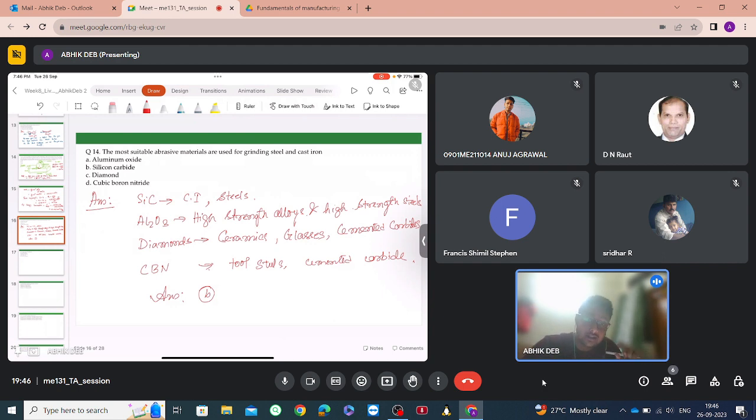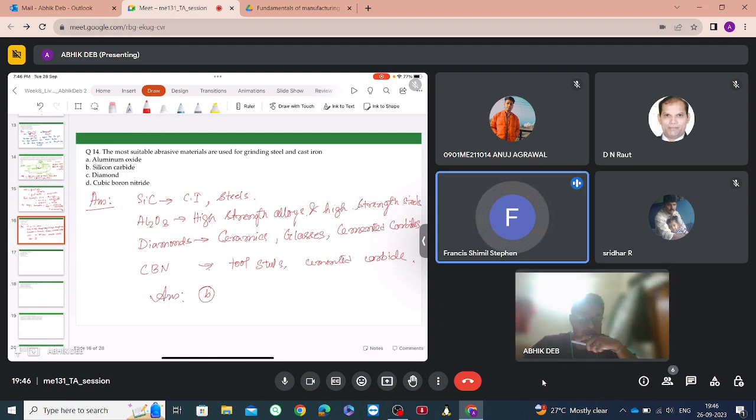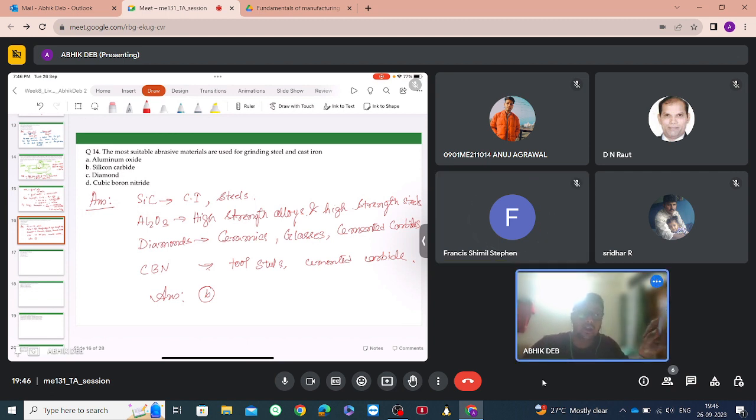High strength alloys, those which have a higher value of yield strength, if they are not brittle, then they also have high toughness. That is, they will undergo plastic deformation significantly, like ductile materials. Can we say they are ductile if they have high strength? Not necessarily. If the toughness or the plastic deformation zone is high, then the material will be ductile.